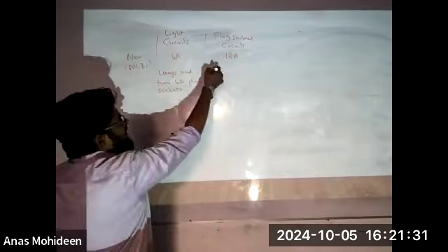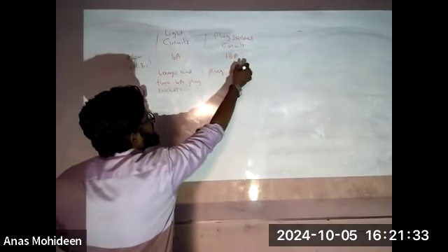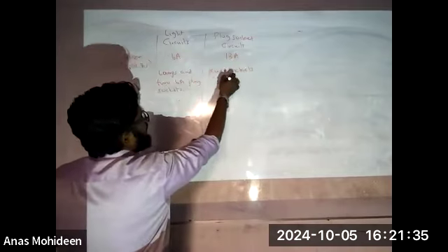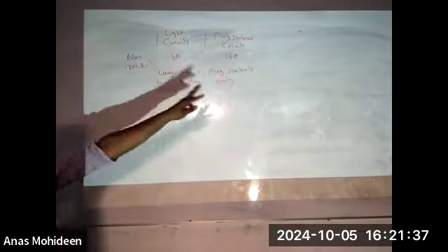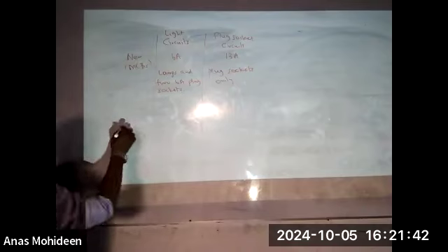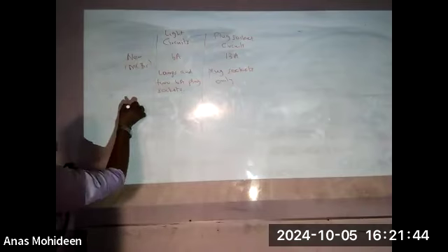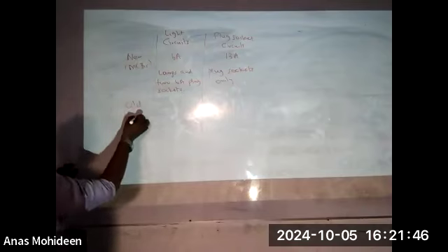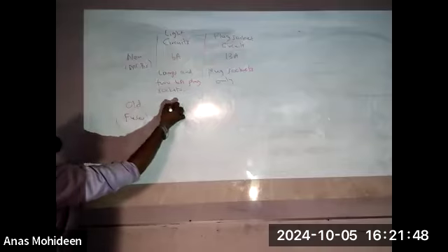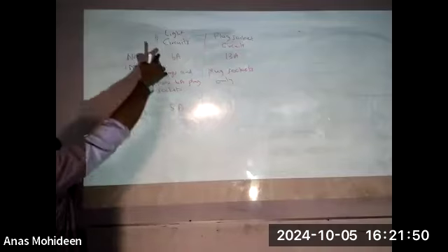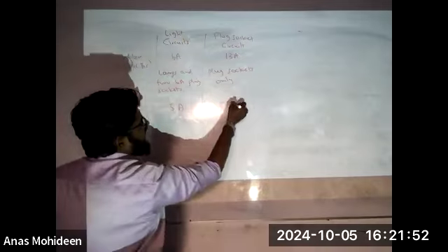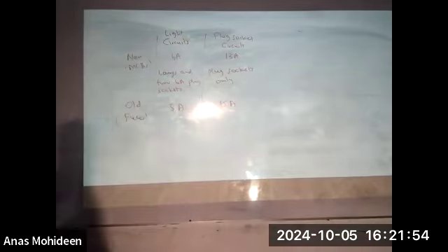And whom can you connect? You can connect plug sockets only. Only the sockets you can connect. You can't connect the lamps here. And also, when you come to the old houses, you had fuses. 5 ampere was the fuse in light circuits and 15 amperes in plug sockets.